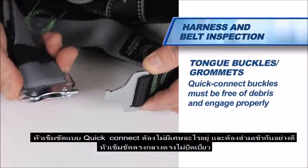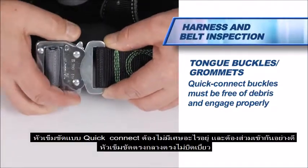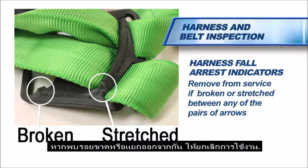Quick connect buckles must be free of debris and engage properly. The outer and center bars must be straight. Inspect fall arrest indicators located on the back D-ring pad for signs of activation. Remove from service if broken or stretched between any of the pairs of arrows.